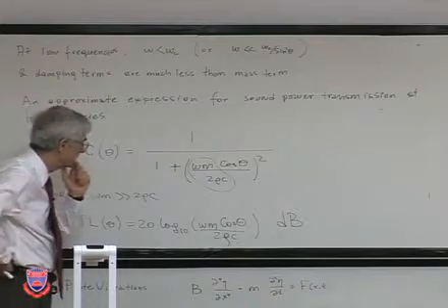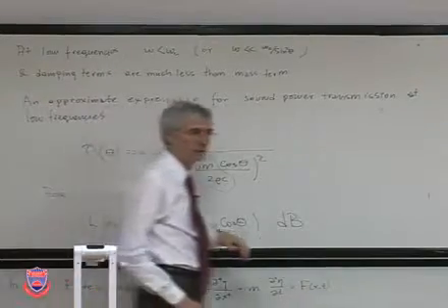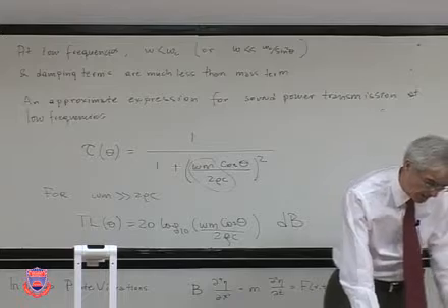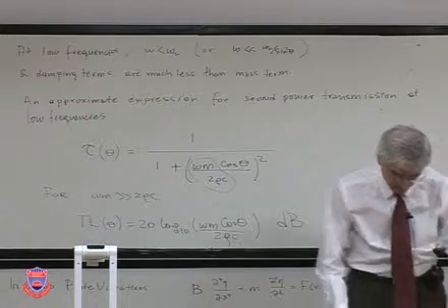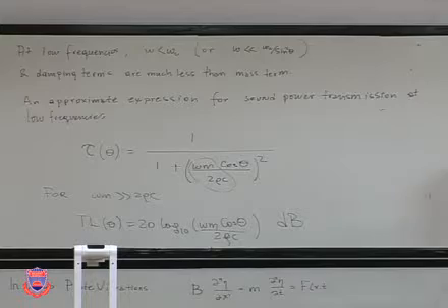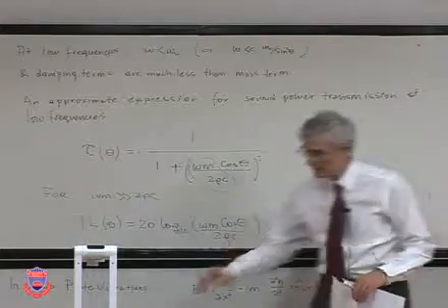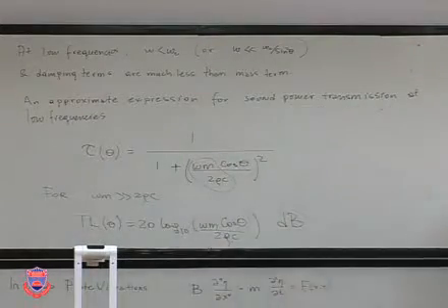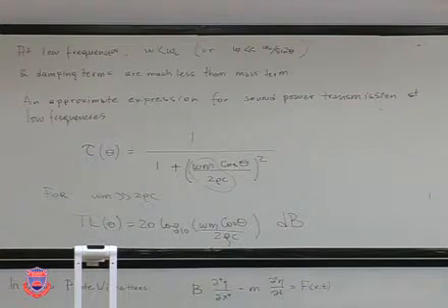Okay. So this is also referred to as the mass law in some cases. Now this is actually forming the basis for noise control studies. And when you look at noise control studies, usually they will give you these equations, this is the transmission loss expression, etc. But where it comes from is what we have just derived.